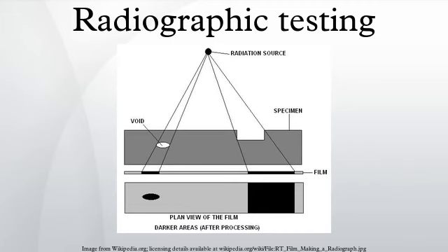The specimen to be inspected is placed between the source of radiation and the detecting device, usually the film in a light-tight holder or cassette, and the radiation is allowed to penetrate the part for the required length of time to be adequately recorded. The result is a two-dimensional projection of the part onto the film, producing a latent image of varying densities according to the amount of radiation reaching each area. It is known as a radiograph, as distinct from a photograph produced by light.